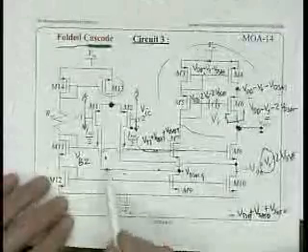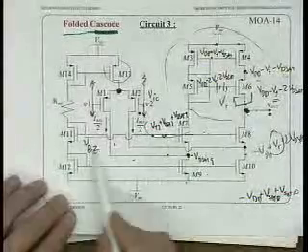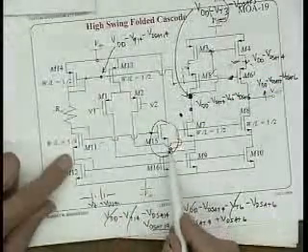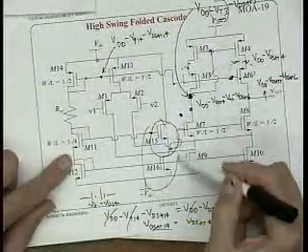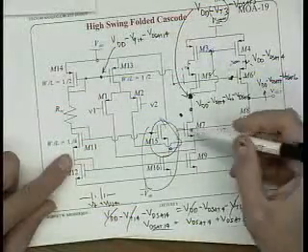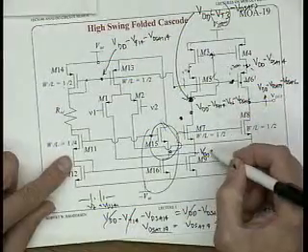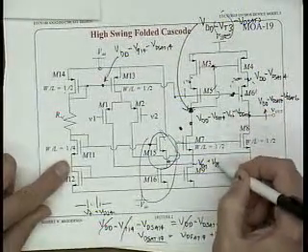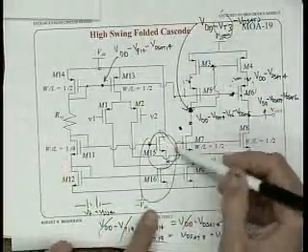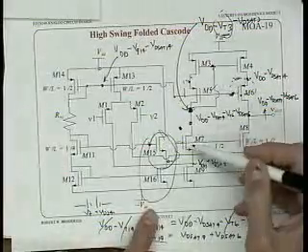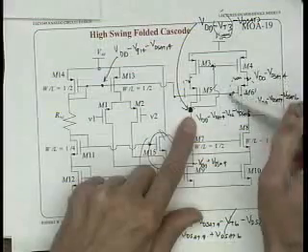See, in this circuit, I take M11 and I just tie it directly over to M7 and M8. That's not the high swing condition. Here I take M11, go through a battery, and then connect to 7 and 8. So that makes it so using M5, 15, and 16 are for the high swing bias of getting M7 and M8 lower. So this is connected to just minus VDD plus VDSAT of transistor 9. So that's what this drops the voltage to do. So we're using a source follower to set the high swing on this lower cascode, and we're using this simple little diode connection strategy up here to set the high swing on the upper one.